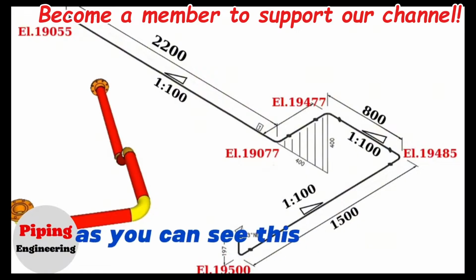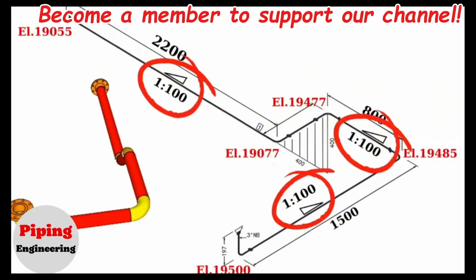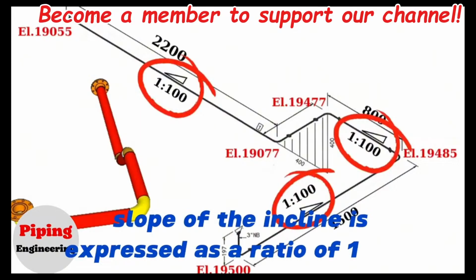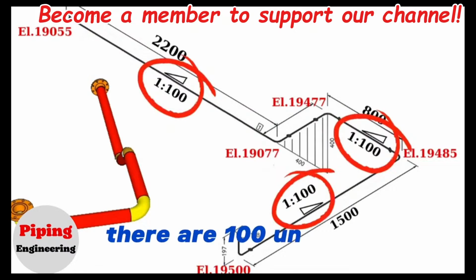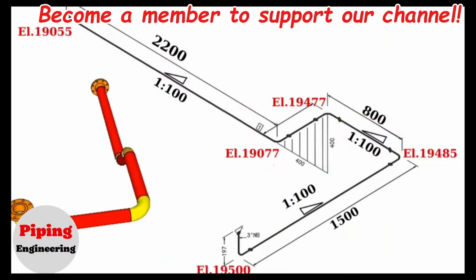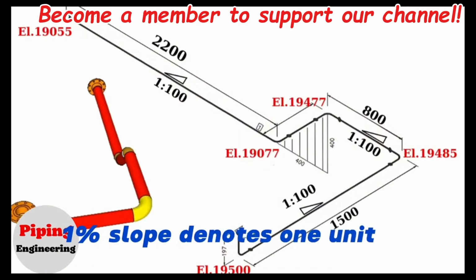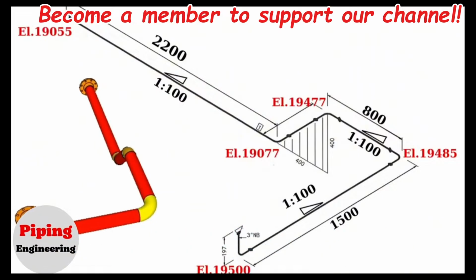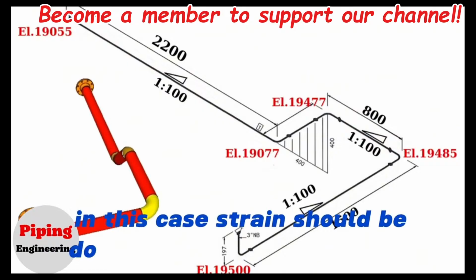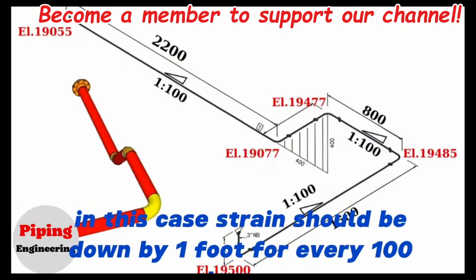As you can see, this is a piping isometric drawing with some slopes and different elevations. In piping isometric drawings, the slopes are shown with this symbol. In this drawing, the slope of the incline is expressed as a ratio of 1 to 100, meaning that for every 1 unit of vertical elevation there are 100 units of horizontal distance. A 1% slope denotes 1 unit rise or fall for every 100 units of horizontal length or distance. In this case, the drain should be down by 1 foot for every 100 of length.